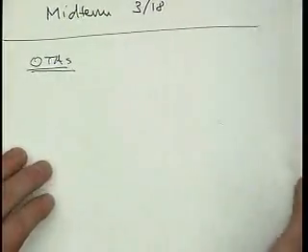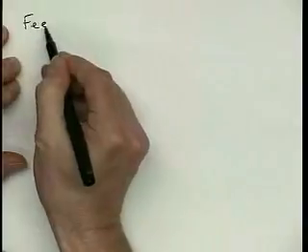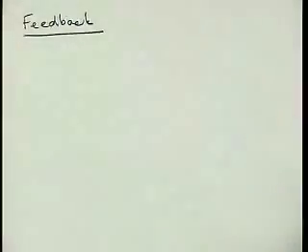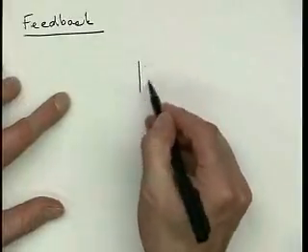Okay, so now there is, of course, the problem. If we can't use a resistor, what are we going to use as the feedback network? Of course, we still need feedback, because otherwise we really can't generate a precise gain over a large, linear input range.